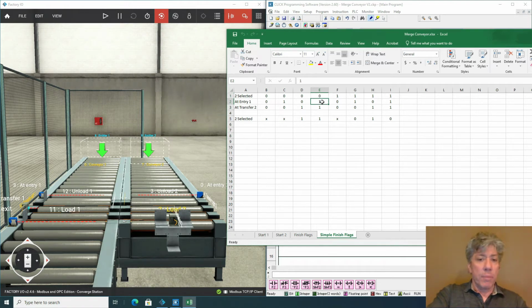Well, there's another one in place ready to go, but wait a second, I just processed something from 1. It's 2's turn because there's something there. This condition is the whole purpose of this bit. It's for taking care of the times when there's an option of processing the pallet from conveyor 1 or 2. So I'm going to choose to process the one from 2 because it's that one's turn.